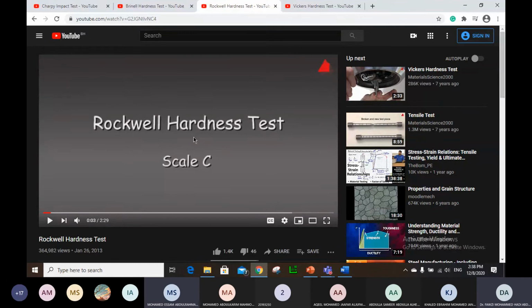The nice thing about the hardness test is that it is very simple, as you have seen, and it takes very little time. In this case, you do not even need to prepare the specimen, since it has a base that you can push on. Finish. You can use it. In addition, it is a non-destructive test. The specimen that you brought, you did the hardness test on it, you can use it in the car or wherever. It's not damaged, right? So it's called a non-destructive test. Yes, you can reuse it. Okay?